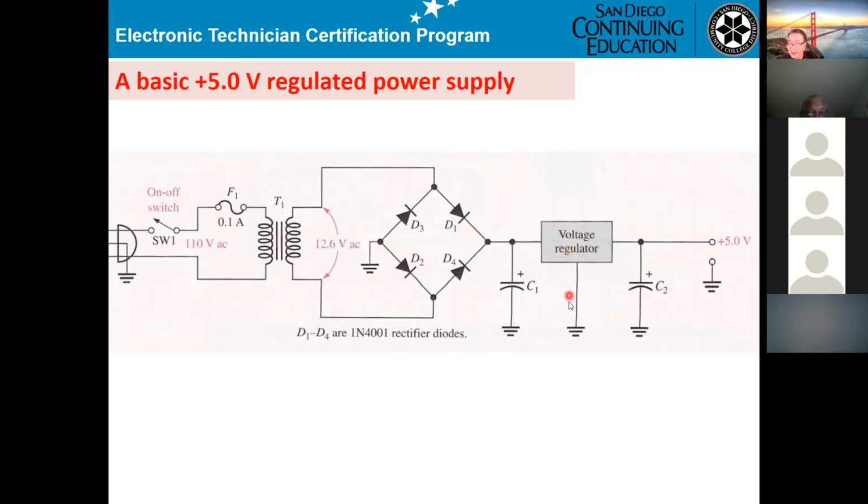You need to replace it. If you find something wrong, you say, okay, I found this one open, not working. What happens? You give this circuitry to the assembler. You say, okay, I want to replace D1, so they can get a new diode and put it in. They give it back to you.